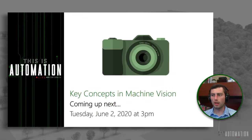All right, so that wraps us up for our quick intro to Powerlink. Hopefully that answers some of your questions as far as how Powerlink works and where you may see it used. Again, just to summarize, one of the key things with Powerlink is its capability to do a really good job in motion control applications because of the direct cross-traffic communication. That's a really strong point of Powerlink. It's also great in those applications where you may need asynchronous data, like standard Ethernet traffic over your field bus line as well.